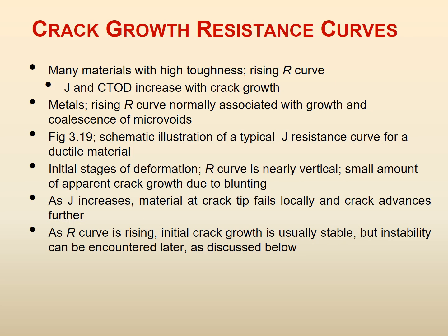With this relationship, now crack growth resistance curves. If you want to talk about crack growth, then it is the energy release rate, which is now non-linear. Earlier it was linear. And when there is energy release rate, the opposite of it is the crack growth resistance curve, right? There was capital G and there was capital R resistance curve. So now we are talking of the resistance of the material.